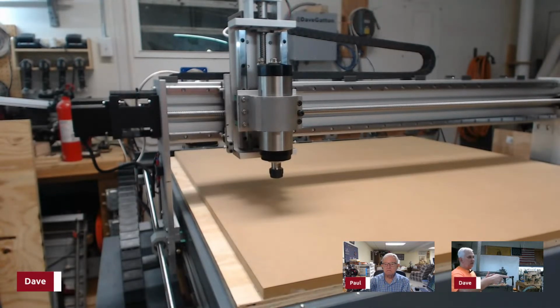But what I did is I loosened the frame on the right side that locks in that piece of sheet metal, that channel. So then as you move it back and forth, the one side's going to move fine, but the other side, if it's the least bit cantywampus, it'll straighten itself out because now it's got room to move. So you run it back and forth, and when you run it to this end, then you tighten those back down, and then you run it to the other end and tighten it back down, and then you shouldn't have any problems.